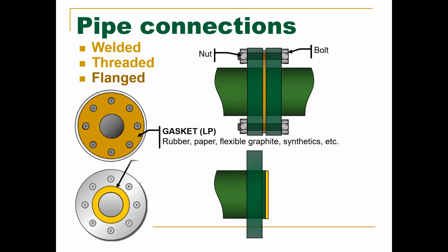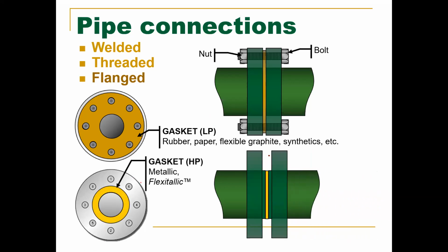Obviously, we have a gasket, but you can tell that there is way more room in between here because that seal is happening between that little piece of metal and our gasket here. And then here are the two different types of gasket material you can use for a high pressure application. These utilize studs. Again, you can use studs on low pressure, and you would probably have to use a higher grade bolt, but more than likely you'll just see studs.